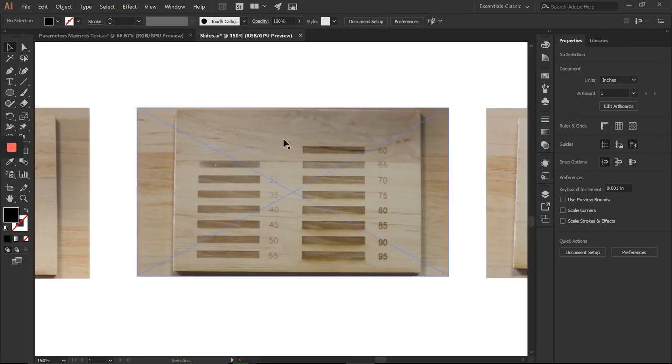As you can see, it's very faint, but we don't get any results when we're running at 30 or 25% power. We start to see an engraving effect once we hit around 40 and 45, but it's still a bit faded. We get a nice contrast around the 55 to 70 range. It's nice and clean. Once we hit the higher percentage power, it gives us a nice contrast, but we also get this burning edge.